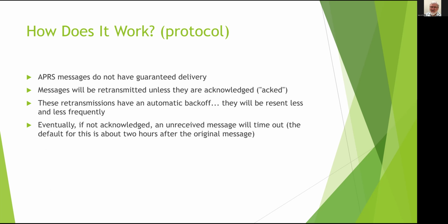APRS has this messaging functionality, right? Messages are not guaranteed to be delivered. Now, APRS will try to deliver them. Okay. So if I send a message to Neil, for example, and he doesn't acknowledge that he received it, my radio will try again several more times, usually for up to about 2 hours.